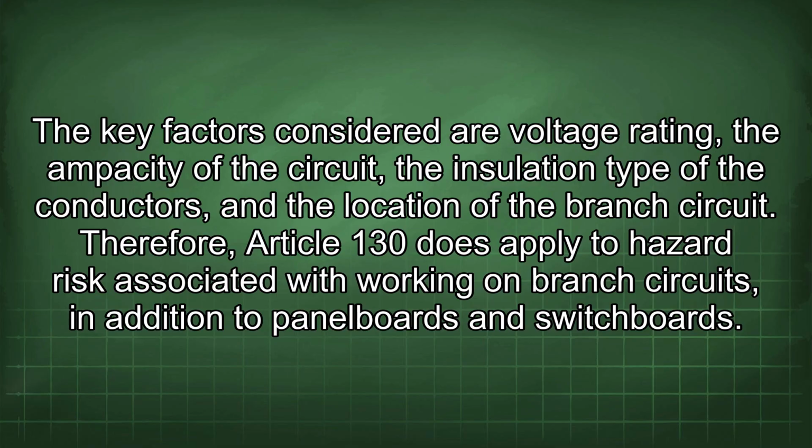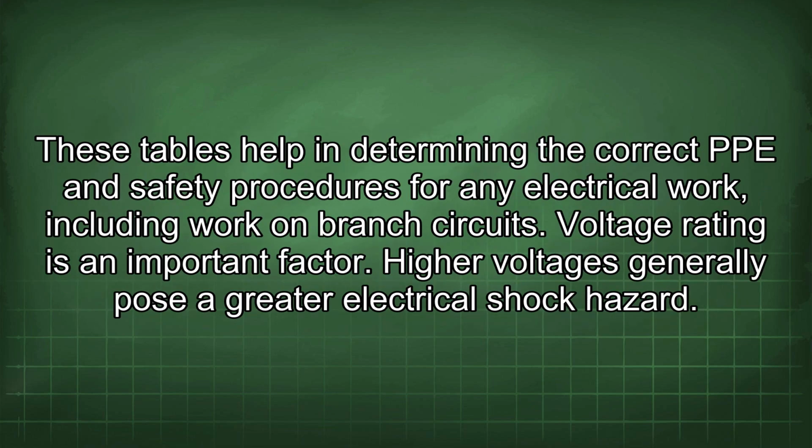Therefore, Article 130 does apply to hazard risk associated with working on branch circuits, in addition to panel boards and switchboards. These tables help in determining the correct PPE and safety procedures for any electrical work, including work on branch circuits. Voltage rating is an important factor. Higher voltages generally pose a greater electrical shock hazard.